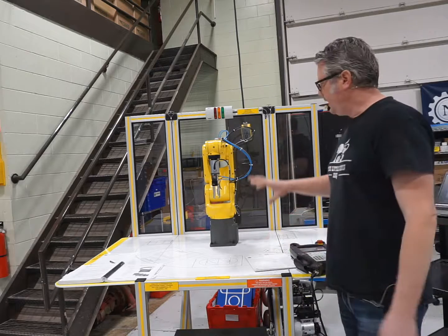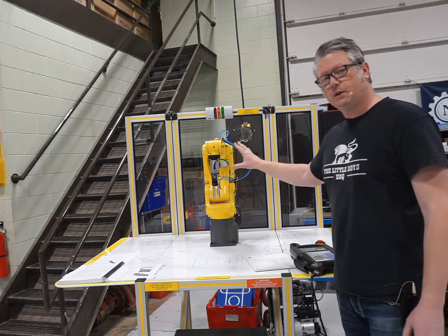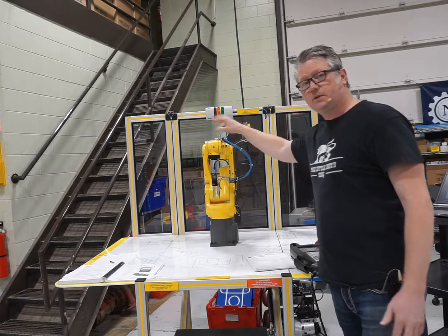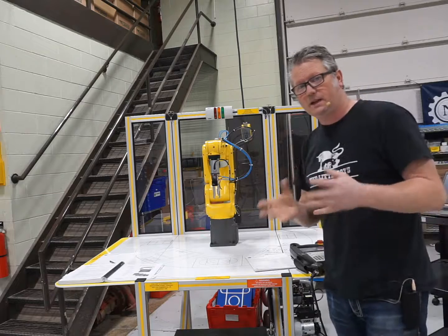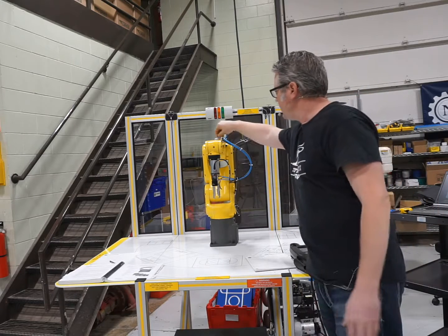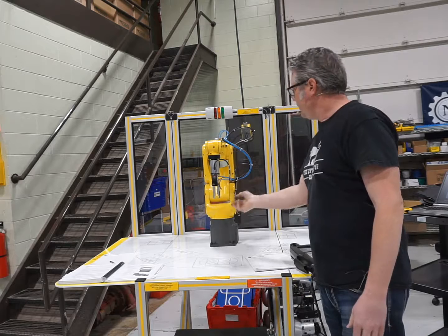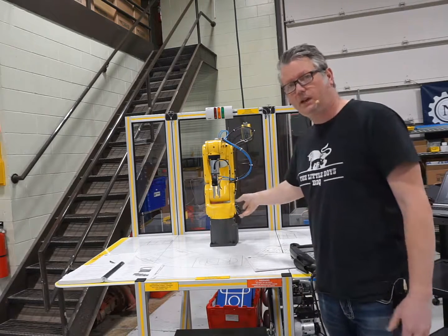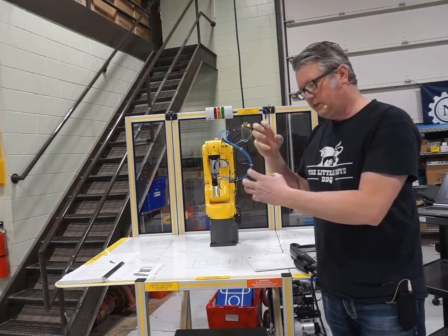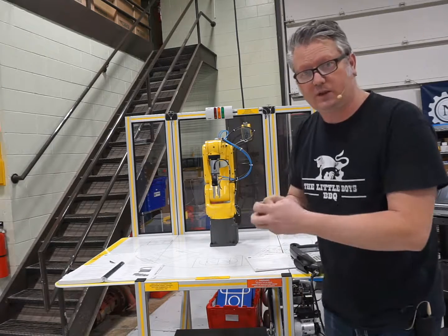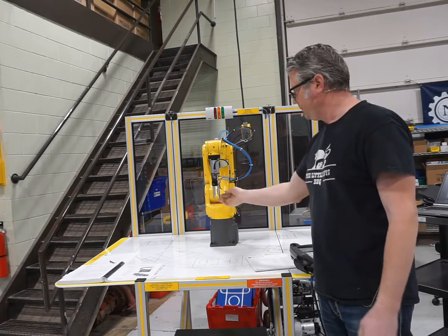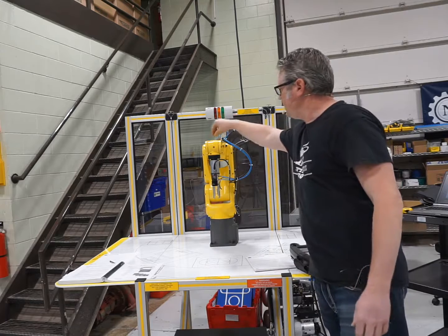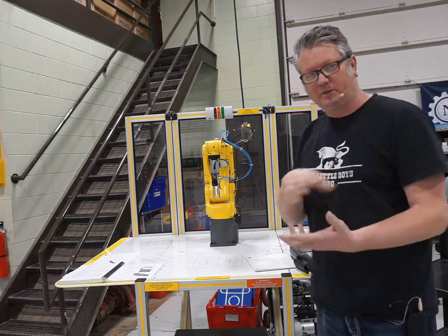So those are all the digital ones. Now, when you're talking about the robot inputs and outputs, this robot has a bunch of outputs, basically some solenoid valves that are built into the robot itself. And those are connected to the gripper, and they're hardwired into it and controlled. There's a connector in the back of the robot that has all of those digital outputs. So a robot output is the gripper. A robot input, there's a connector up here that's covered with a dust cap, and it's got a number of pins on that.